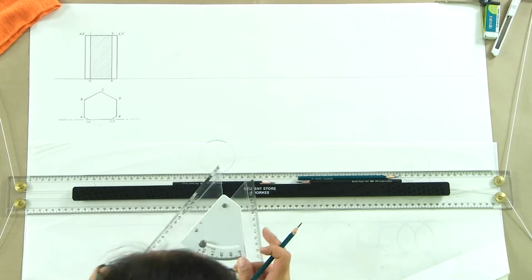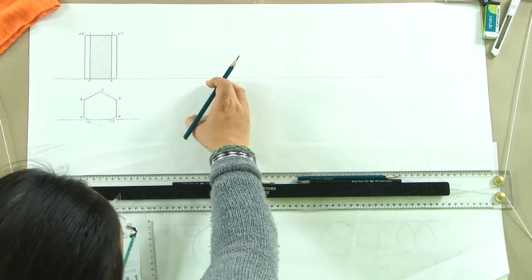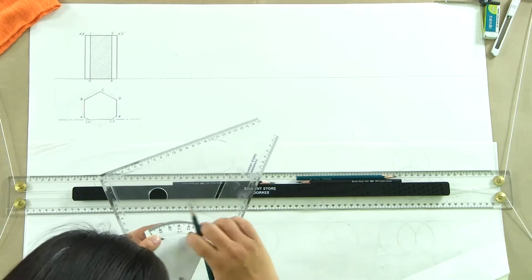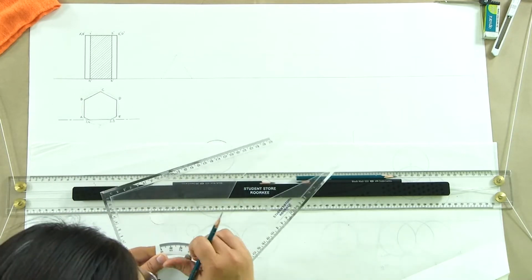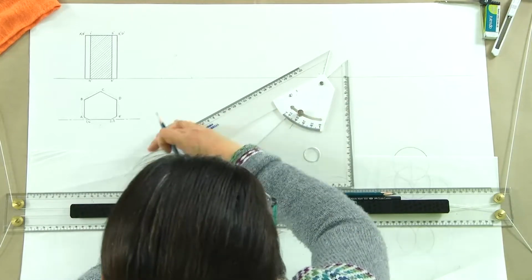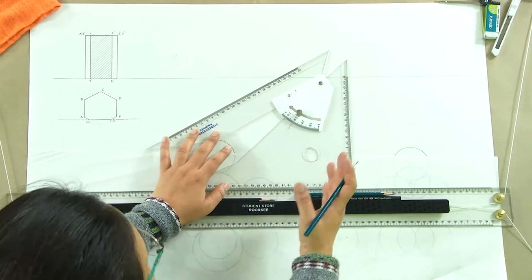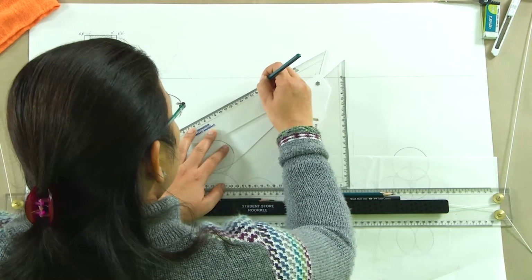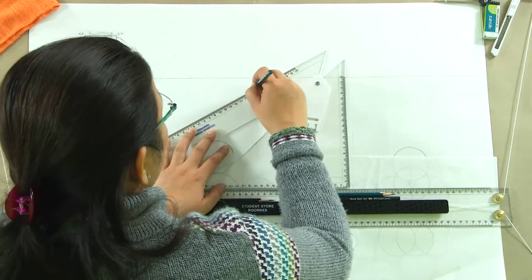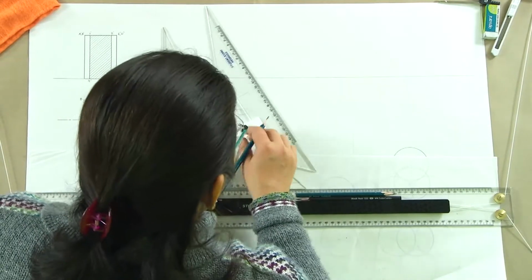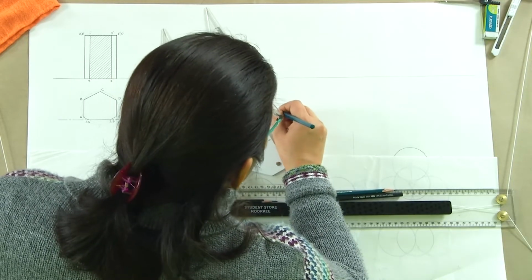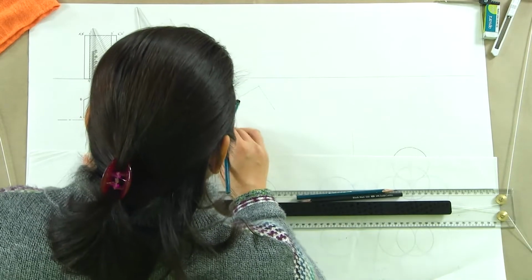Now we are assuming that this triangular prism is kept and it is inclined at certain angles, say 30 degrees to VP. So what do we do? What we will actually get is a prism which is inclined like this. So we get a rectangle, assuming the height of the prism to be, say, 10 centimeters. This is the height of the prism. The triangle is 5 centimeter side and it is kept on HP. So we see complete 5 centimeters here.